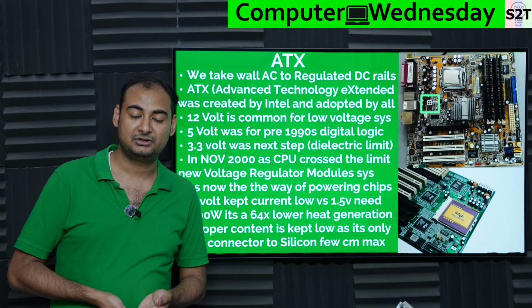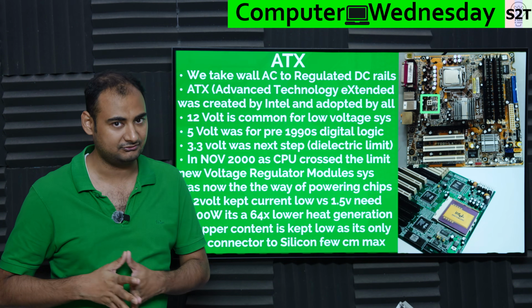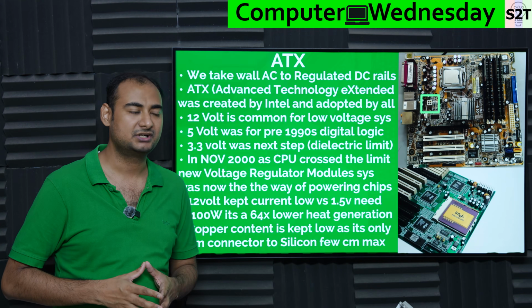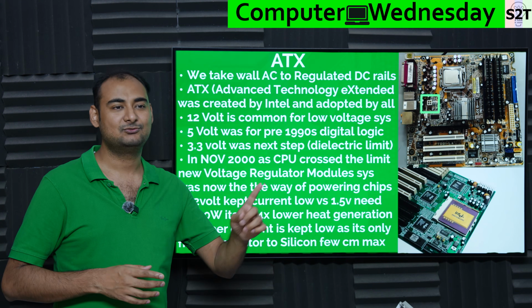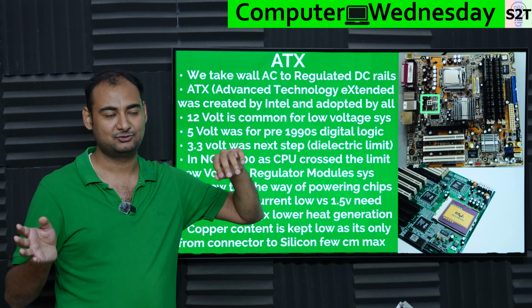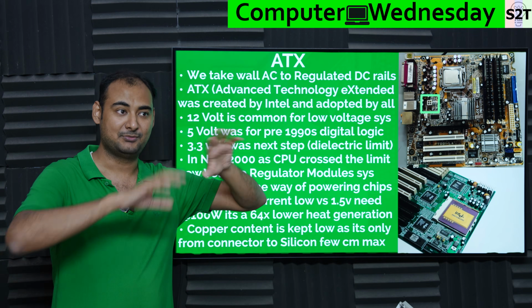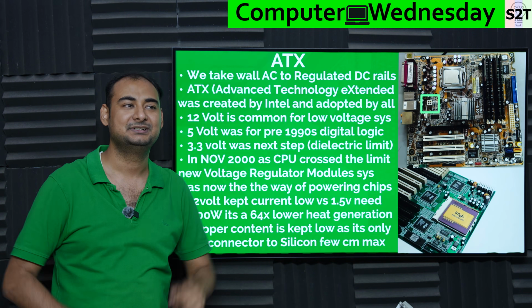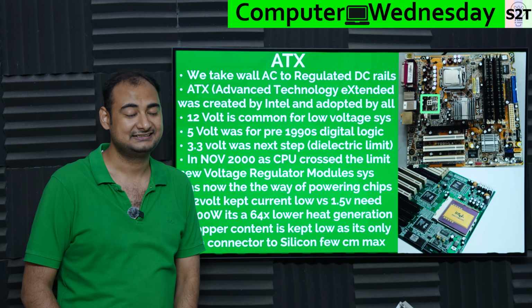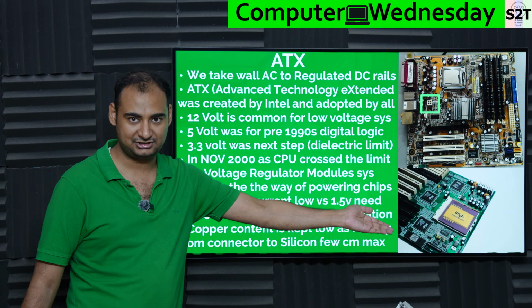But if you are reaching a point where your CPU is consuming hundreds of watts, or at that time like 100 watts, 100 watts at 1 volt simply means you have to have that many amps at a higher voltage like 12 volt, burn off 11 volt at that many amps. And I'm like, wait a minute, that's a heater. Yeah, that's why you can't use a linear power supply for newer chips.